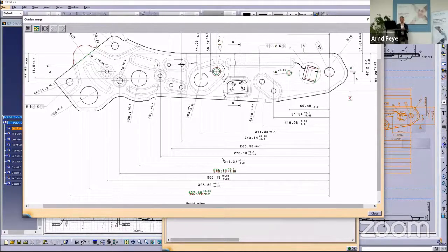This also works for views that are moved on the sheet. So if you have a front view and everything is organized differently on the new revision of the sheet, this will be repositioned automatically by xCompare, and you have a very proper overview of the views and the differences.